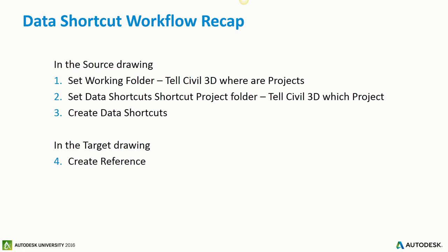One challenge that I had with all the Caltrans employees on this was making sure that on the prospector tab, you know this is drawing on the top and data shortcuts are at the bottom. So that was one very important thing for them to understand: am I browsing the drawing or am I browsing the project? So it was a big thing to harp on that here, this is your drawing, this is what you see in the drawing, and this is what is available. Maybe you did not create it, somebody else did, but it's available for you to bring it in.